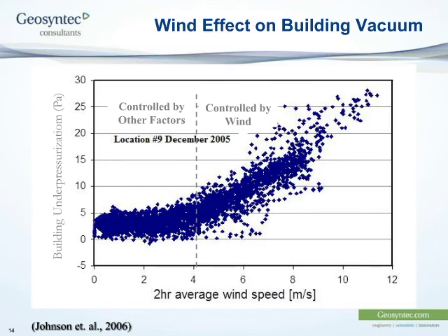And the reason for this is the same as the reason why airplanes fly. When the wind goes very quickly over the wing of an airplane, it creates lift. And when wind goes over the roof of a building, it creates suction as well. And so you can see that you can get very strong underpressurization of a building if the wind blows. And we know that winds blow.